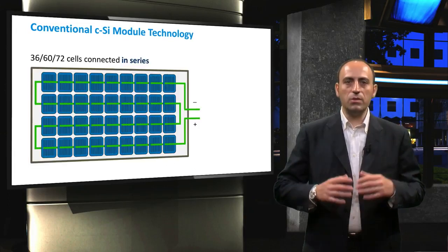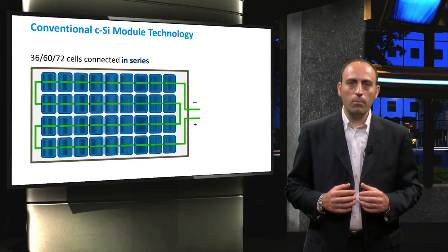When we consider a series connection at module level, we may end up with this 36 cell structure. This module has 36 solar cells, but nowadays it is also possible to find different types of modules that achieve high voltage levels by interconnecting 60, 72, or even 96 solar cells in series. A high output voltage minimizes the resistive losses, which depend on the current flow through the metallic grids, and enables highly efficient operation of the inverter, which we will discuss further on.